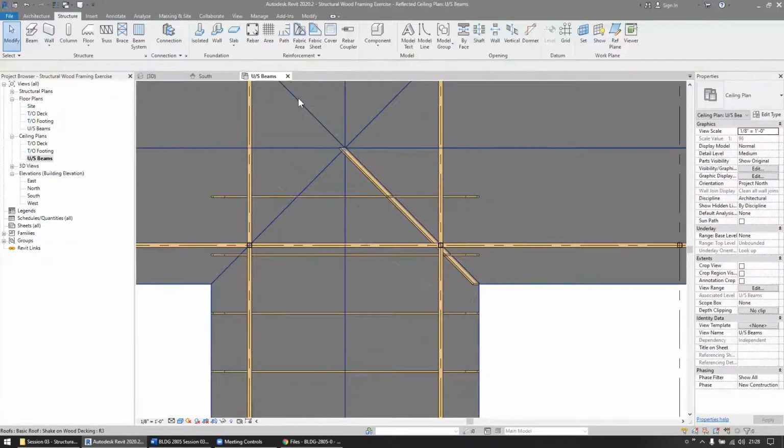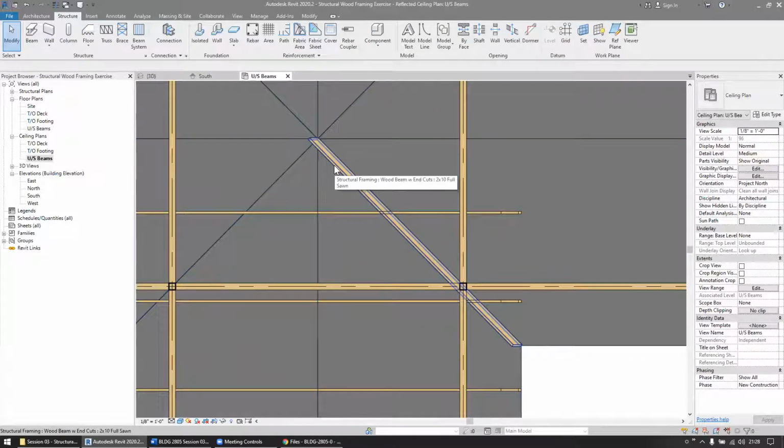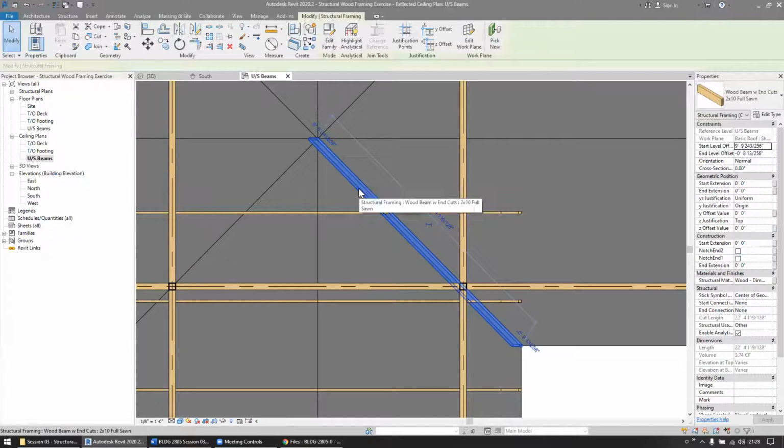Now, after I'm done, you can see here the beam seems to be not vertical, and it isn't, in fact. The top of the beam, because we do it on a 45-degree angle, it's flush to the underside of the wood of the roof. So it's not vertical.